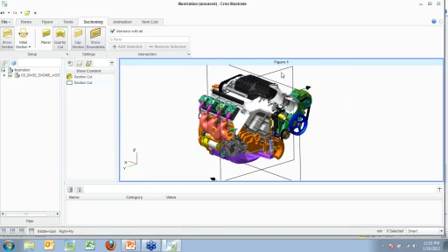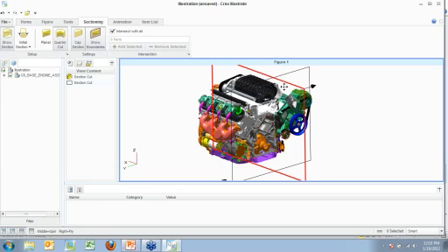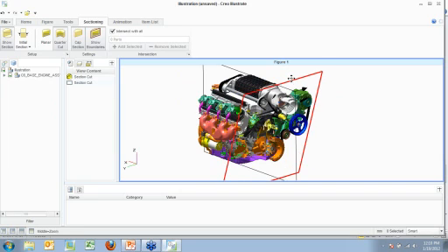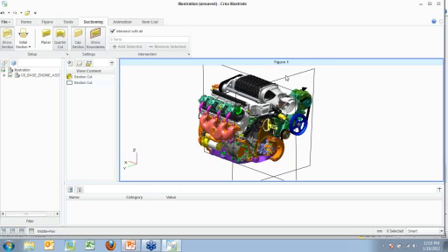And in addition to dragging like that normal to the plane, you can also hold down Control and drag the plane. It'll rotate around one axis. Or you can hold down Shift and drag, and it'll rotate around another axis.